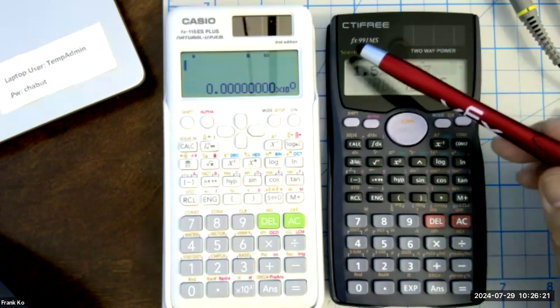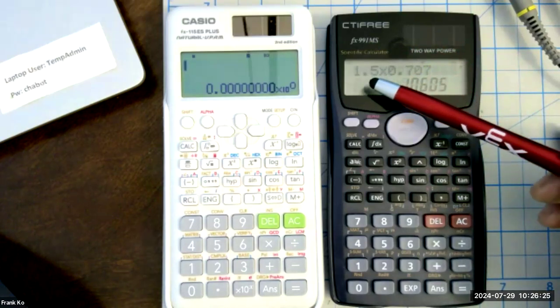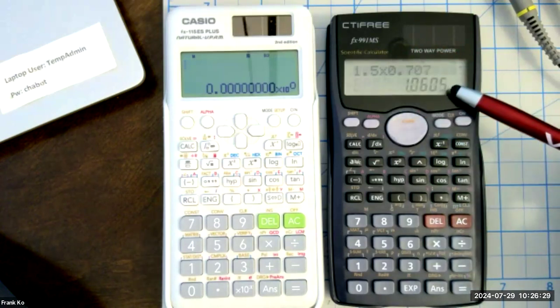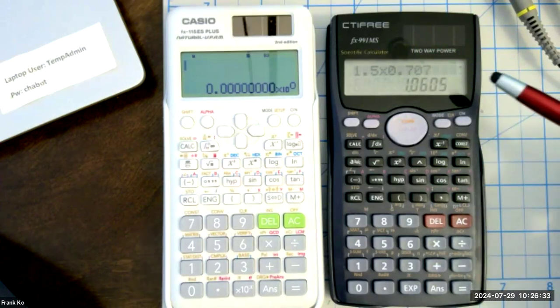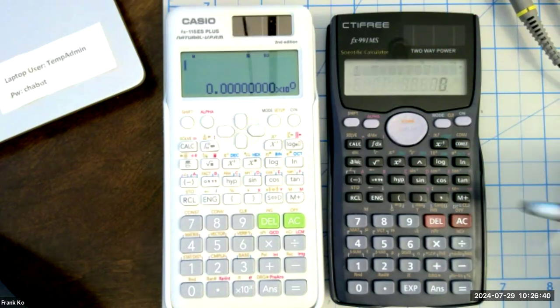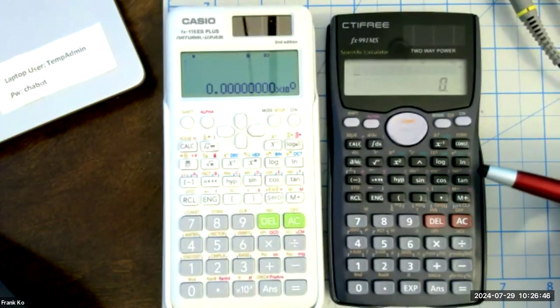Okay, the 1.5 started off as a V with a subscript P for volt peak. And this answer we would write as 1.06. Again, we round to 2 digits after the decimal point, VRMS. Now, clear? And the next voltage calculation at point B is actually the sum of the previously calculated values.